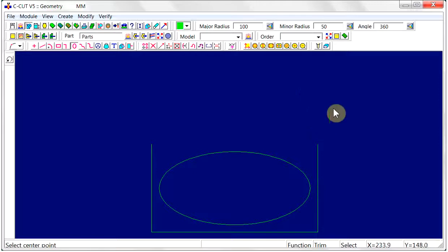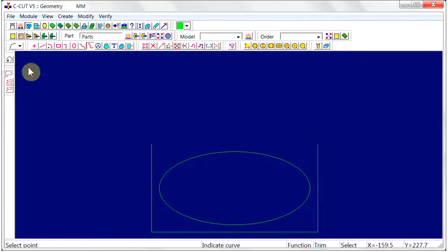We want the spline to have a saddle shape. We select the spline function and subfunction direction ends. A direction end, unlike a free end, implies that the first or the last point of the spline is not part of the spline and used only as a direction point for the spline beginning or end.